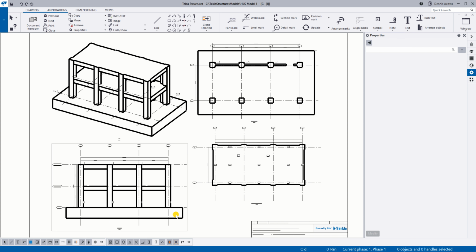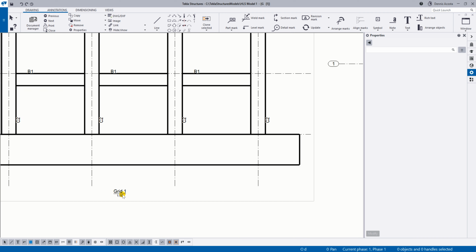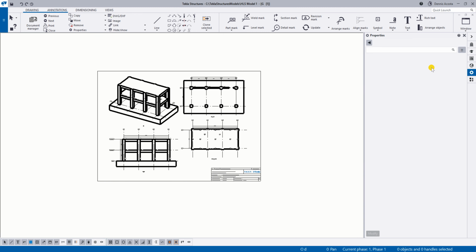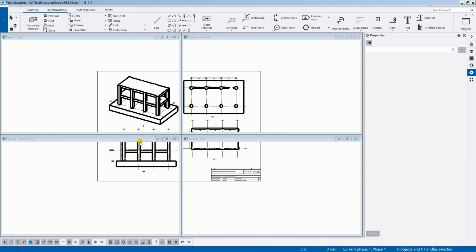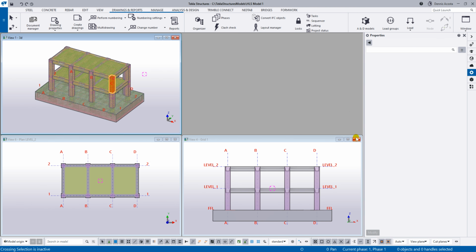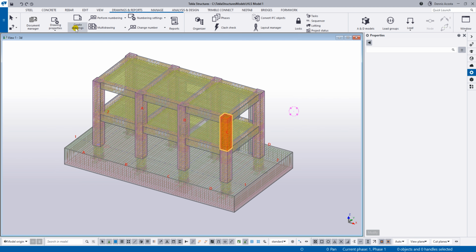Okay. For the next one, let us create the grid 2. Grid 2, the one with the wall. Okay? So, just close it. Say yes. Now, on the grid 2, again, create drawing or create GA drawing.